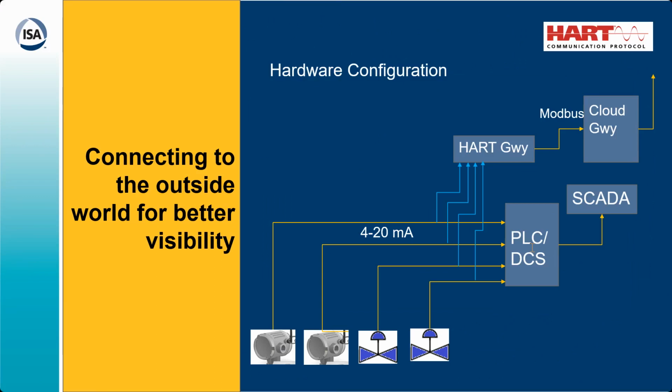But latency is not important as far as wired HART is concerned because it is not used in control. The 4-20 milliampere signal is used in the control, and all the data used to build the analytics and to understand instrument diagnostics and other faults, the HART technology is used for that. So latency is not very important in this application. For wireless HART, there's TDMA and a predictable latency.